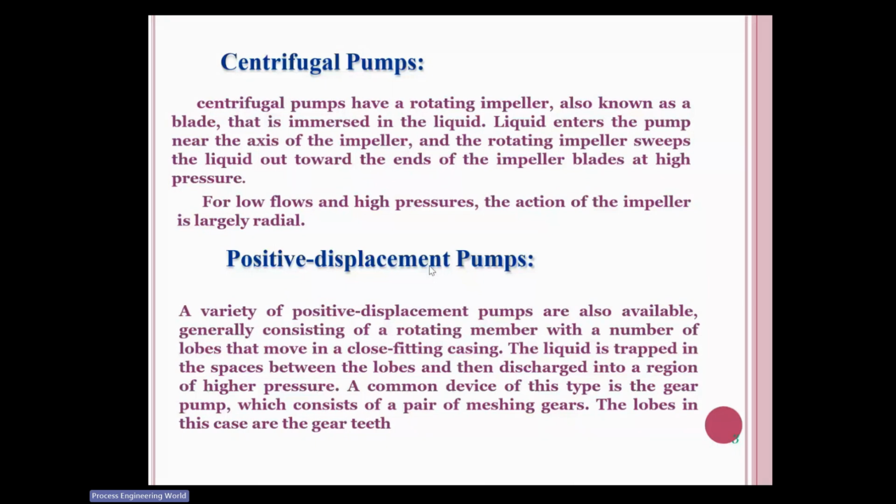It is moving horizontally. When it is moving horizontally to the left side, at that time the suction takes place but the discharge is stopped, and when the piston or plunger moves horizontally again to the right side, at that time the suction is stopped and the discharge is started. So that's why you have a pulse with each stroke, or each time a pumping chamber opens to an outlet port.